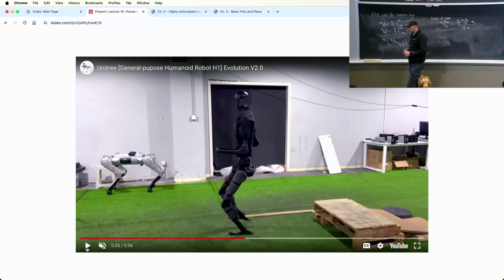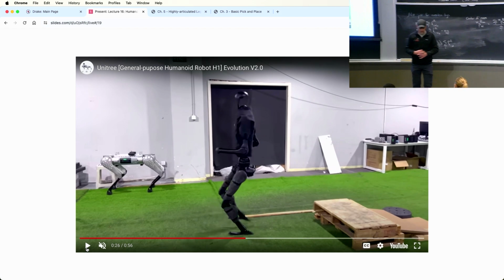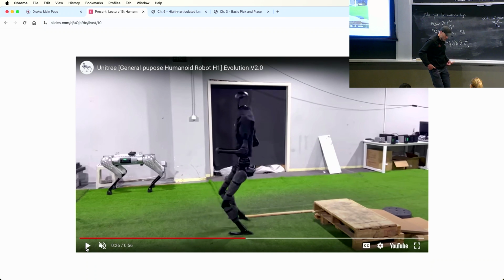So the question is, what are the more lifelike approaches? A lot of people noticed that was a problem and started working on different ways to get around that. I've seen robots still using ZMP that had, for instance, an extra joint in the toe. They would tend to have slightly big toes, but you could move into a smaller support polygon on your toe. That was a good idea. I've seen people add hip joints so that even if your leg is straight, your hip can give you something that avoids the singularity.